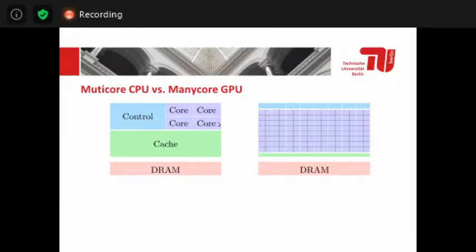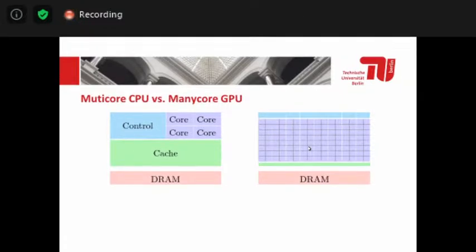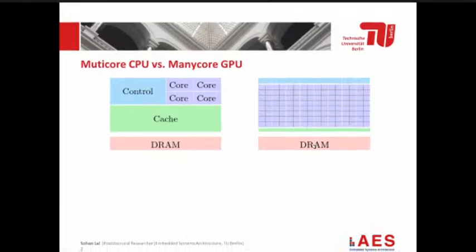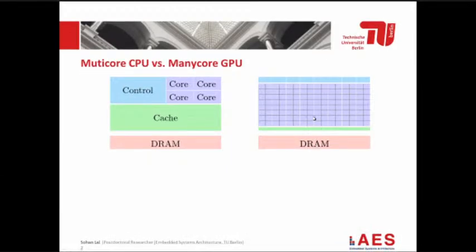If you compare this to a CPU, then a GPU has many small cores. To give you a perspective, a latest GPU from NVIDIA, for example, can have more than 4,000 cores. The caches in GPUs are very small. Essentially, if you compare the per-core cache available in a GPU to a CPU, it's very tiny. The control logic is also very simple. The GPU has a high-bandwidth DRAM.